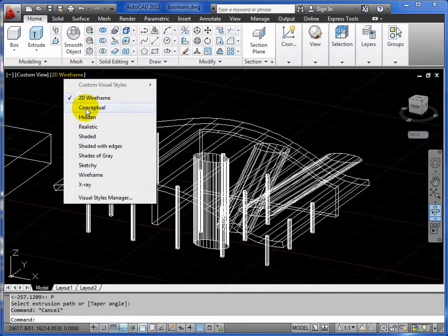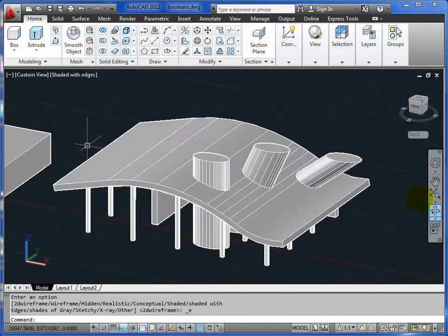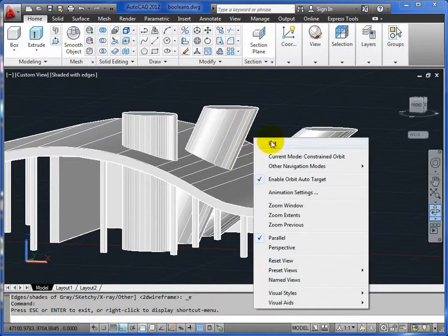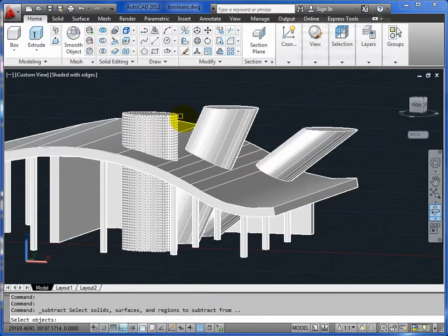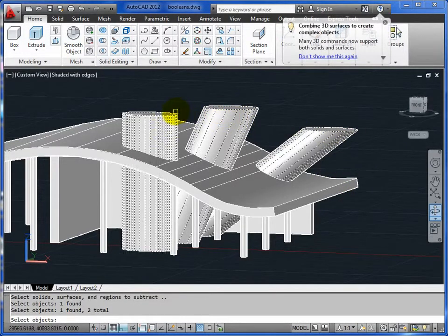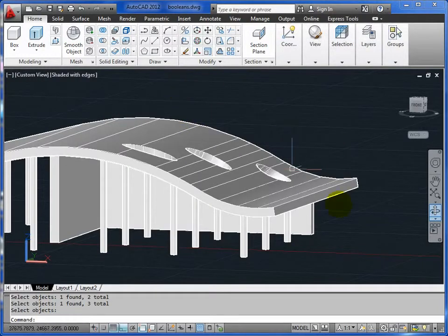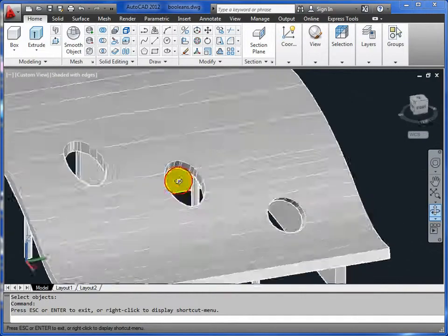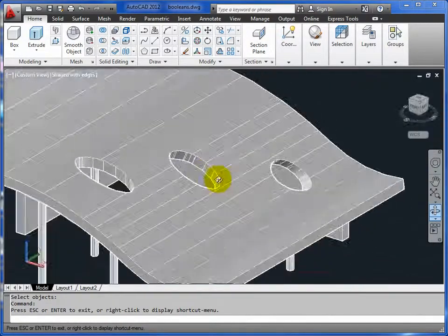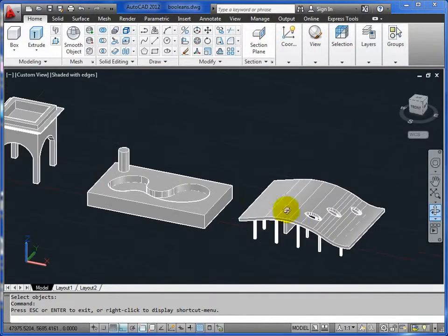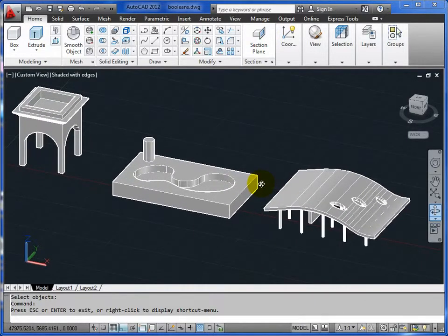Okay, so it looks a wee bit bizarre at the moment, a bit like a kind of chimneys on an ocean liner or something. Okay, quite funky in their own right, some kind of expo building. Okay, then do the subtraction. So you pick your roof shape and return, and then your 3 chimneys get chopped right the way through it. Lovely and easy. Okay, so because of the angle, the shapes are changing, and because of the slope, that affects that as well. So as you can see, Booleans, extremely useful modeling editing tools.